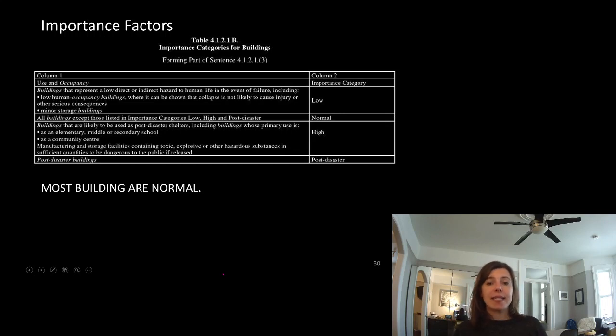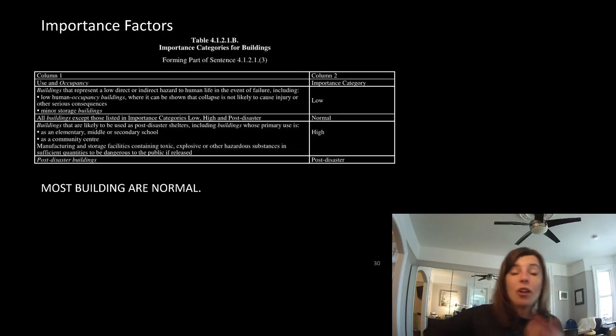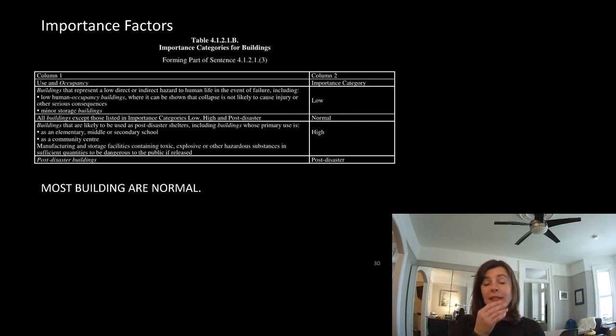All right, the next topic we're going to talk about is climatic data, or the things acting on our building from outside. Up till now, we've been picking what the loads are. I mean, we're picking what type of building we're making, so we're picking the live loads that go in it. I mean, our client is ultimately making that choice, but that's coming from us. We are choosing the assembly, so we're technically in control of these dead loads. The environmental, or the climatic loads, are a little bit different.